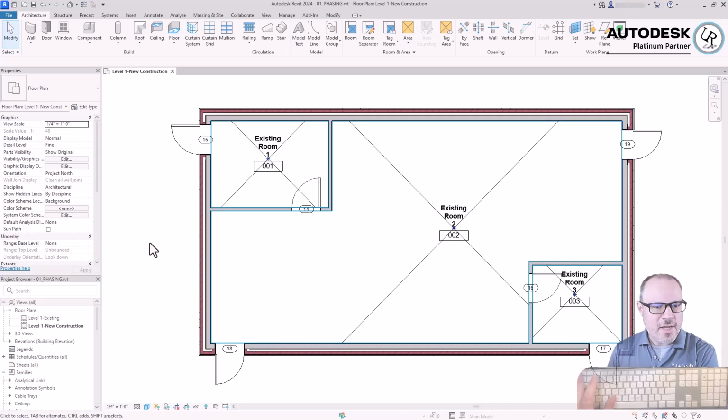All of this information now shows as an existing building. So this would be as if you were walking up to a project before any modification was started for this building's modification. You must bring in all of the existing content that is going to be adjusted and modified and utilized or interfaced with from the project inside of your Revit software. It has to exist in the existing condition for the phasing to take place.